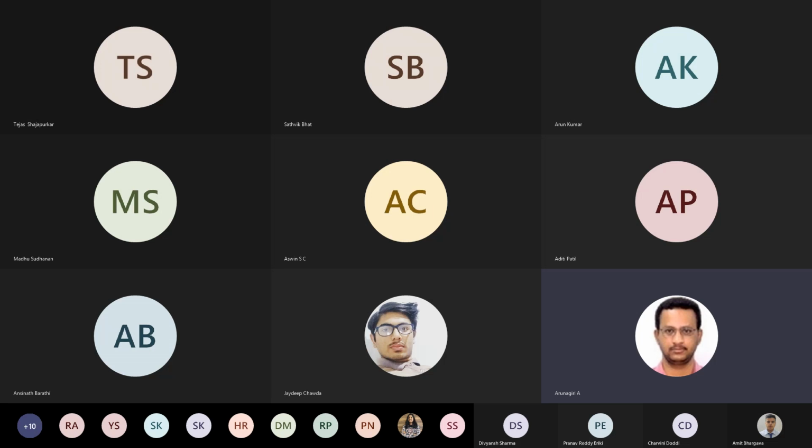Okay, so what are all the factors to be considered while selecting the type of heat exchanger? That is maintenance, cleaning, thermal expansion, size of the shell, and heat transfer coefficient, because the heat transfer coefficient may suffer due to the bypass area. Then cost of the exchanger, and the number of tube passes. Sometimes the number of tube passes can be selected based on the diameter of the shell. If it is more than 1200 mm, in such cases we have to go for more passes, 8 to 12 passes, like that. Then the nature of the plant. So these are all the things that we have to consider.